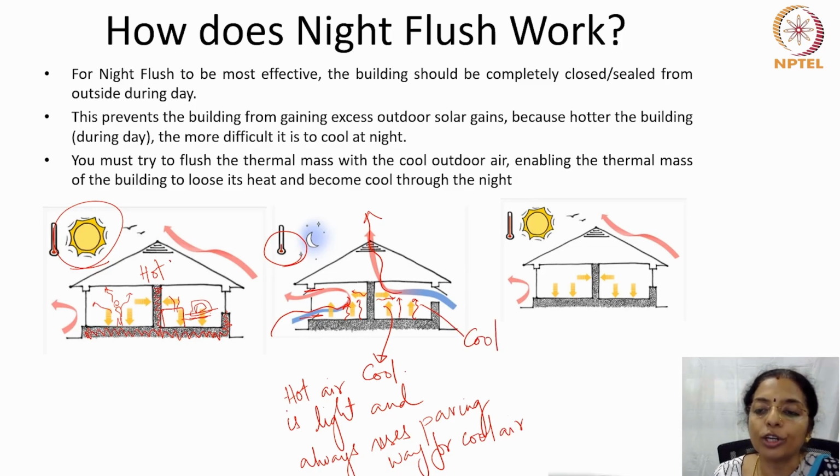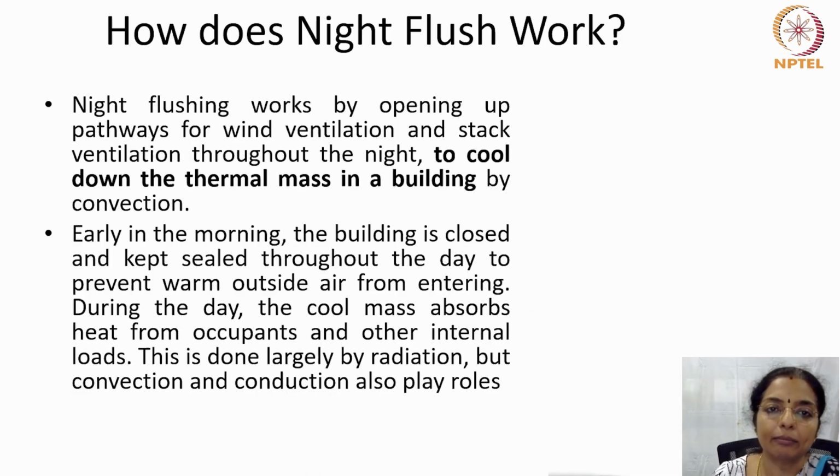At that time, what should you do? You should close all the openings. So the inside remains cool during the day, and in the evening again, as the people and the contraptions have radiated the heat and the indoors become warm, again open the window at night and continue this cycle.